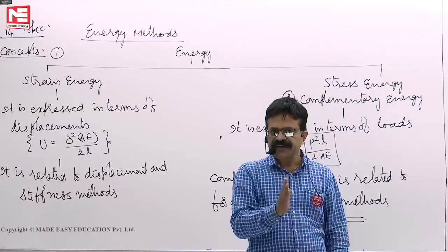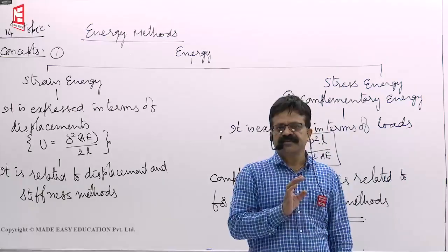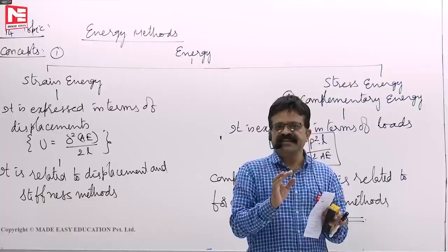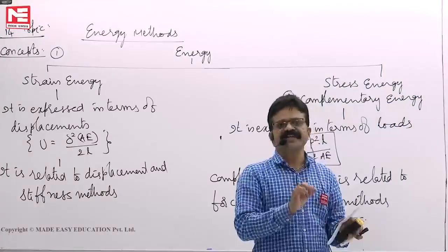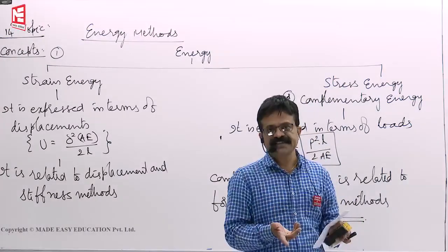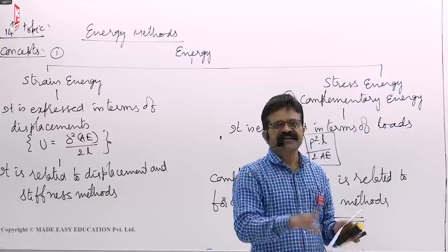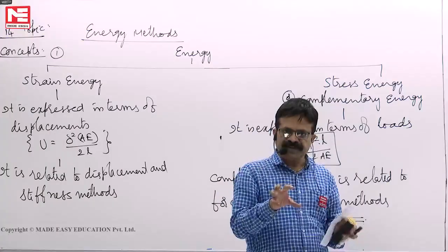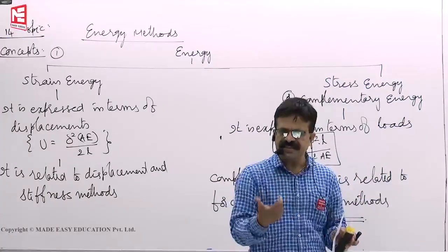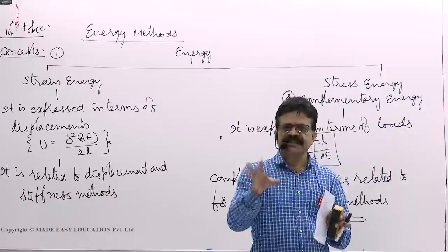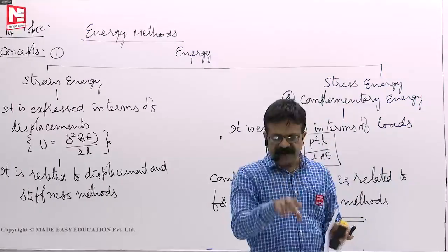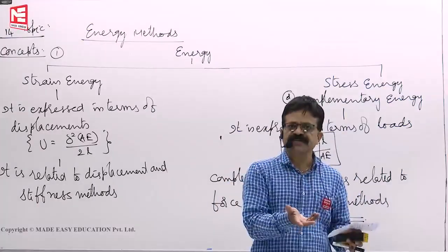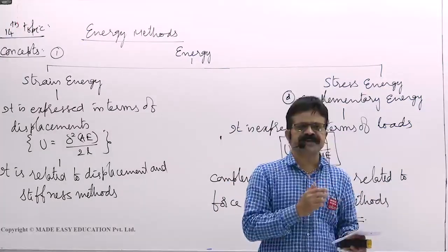Now stress is a function of load and area. As the load increases, stress will not increase linearly because the stress is a function of area also, and area is continuously changing. So non-linearity will exist because the geometry is changing.